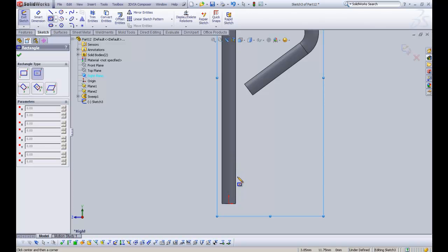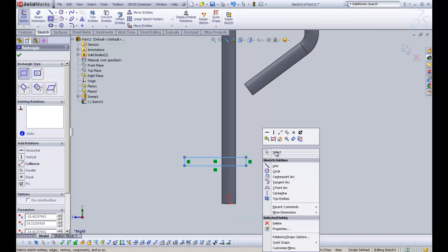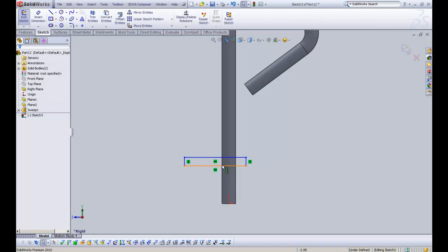Centre rectangles are a little bit more advantageous than using the corner rectangles for this. What we're going to do is create some steps, and if I drag them there, you can see that there's no relation at all to the handrails. It's just there, and then we have to add some dimensions. It just takes a little bit of time.